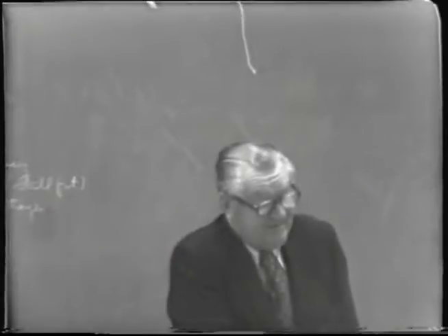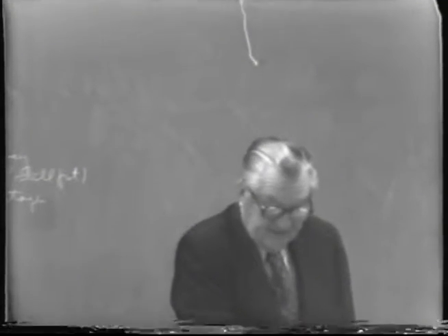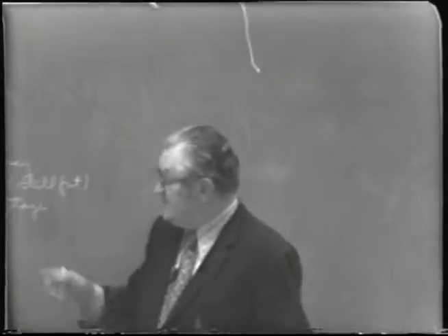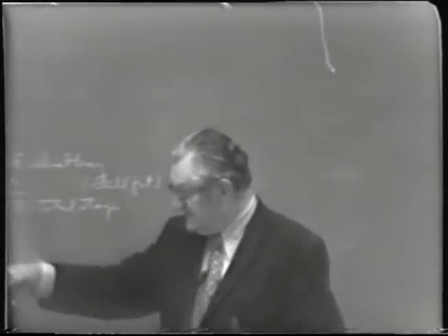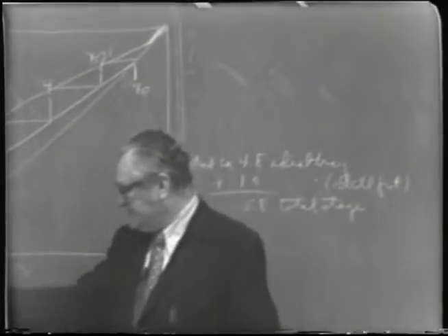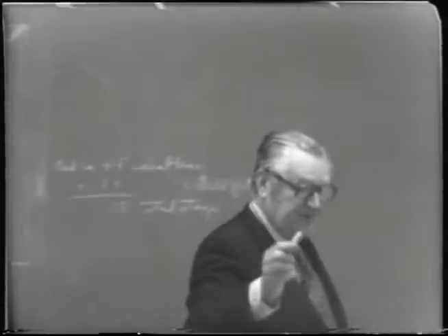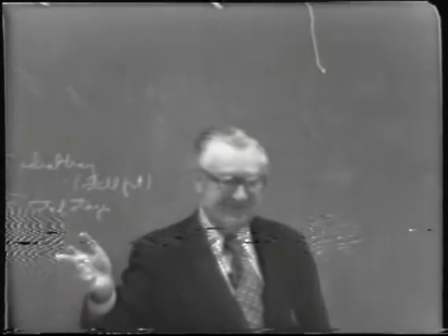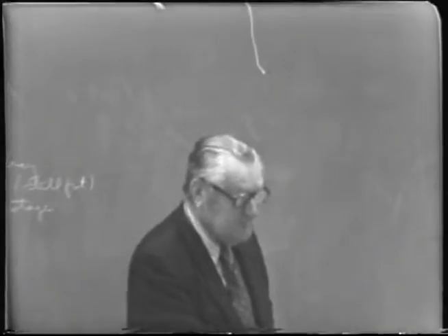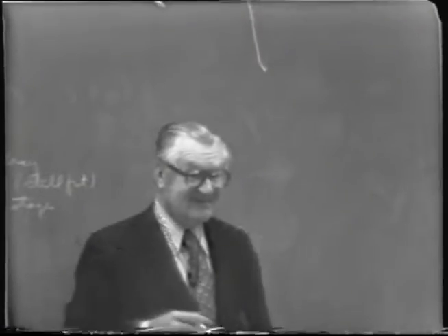Of course, in real practical problems where you're dealing with separations into essentially pure components, at least in the case of alcohol, where you're trying to get essentially water as the bottoms product, we're really dealing in terms of 20 or 30, 40 maybe ideal trays in a practical problem. So arguing about 1 or 2 or a fraction of 1 is quite academic.